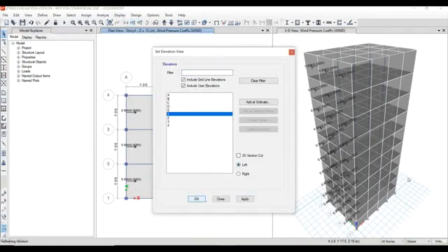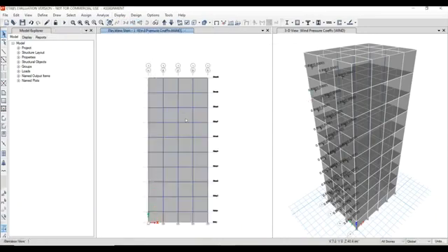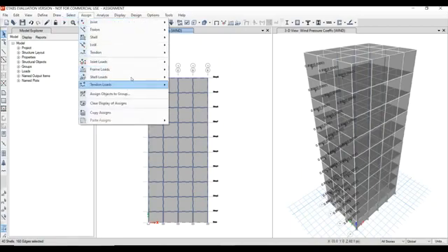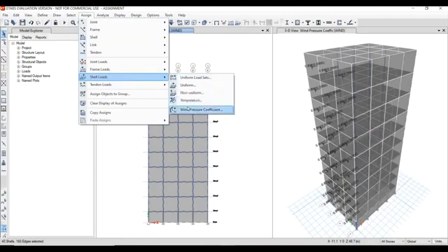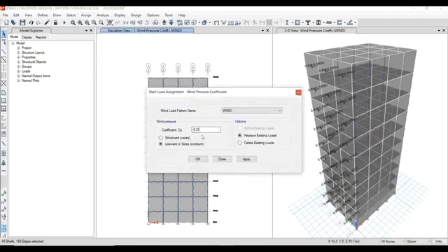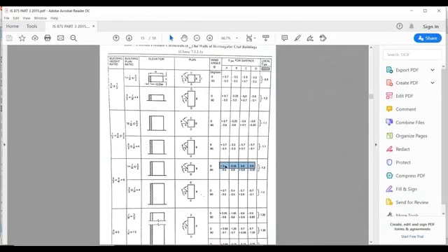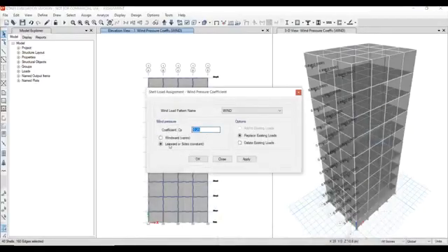OK. And now click every shell, so that we need to select it, and now we need to assign shell loads, wind pressure coefficient. For the wind pressure coefficient we have minus 0.8 and minus 0.8. So minus 0.8, leeward direction or sideward, constant. Okay.